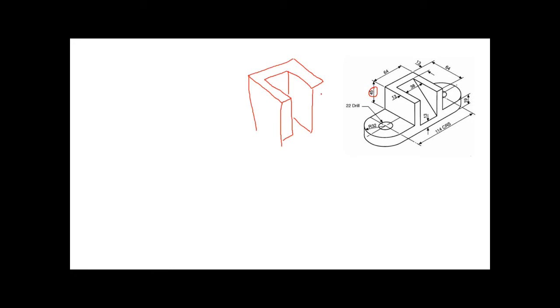And I did the angle, the triangle. You create a triangle here, and then you make a press pull like this. Okay, but be careful. This distance is 45 up to the surface of the base, but this one is a little bit down. So your depth should not be 45.